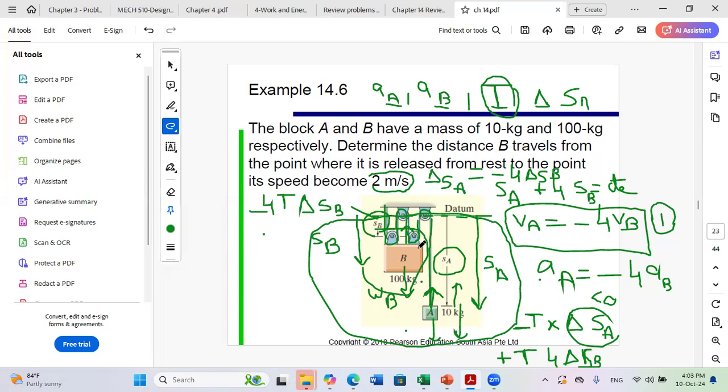So you just have the work of weight of A and the work of weight of B. You have external forces here, which are the reactions at the supports, but the support is fixed, it's not moving. Whenever you have a force applied at a fixed level, it cannot produce any work, so the work at this level will be 0.